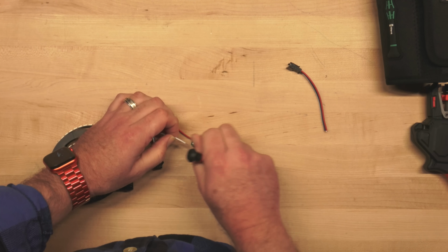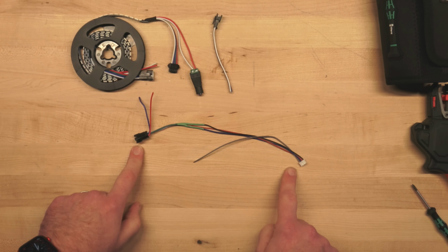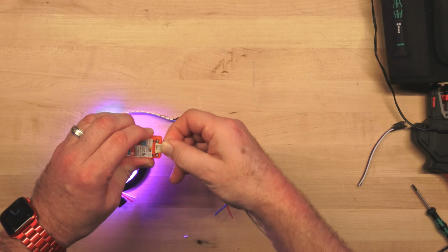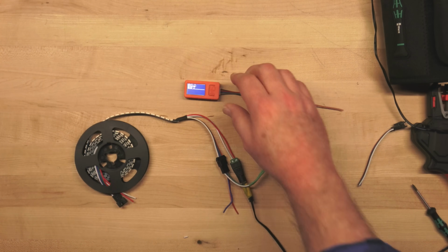There are 2 ways that you can connect the M5 module to the strip. Either way, you'll need a connector. The simplest way I figure is to grab what's commonly known as a Grove port connector, which has 4 wires coming out. It supplies a connection for the ground signal, the power signal, which we'll ignore, and 2 signal lines, of which we need only 1. And so the port has 4 pins, of which we're going to connect only 2. You'll leave the module's red power wire and the second data wire unconnected, as they're not needed for this project and can cause problems if you do connect them.